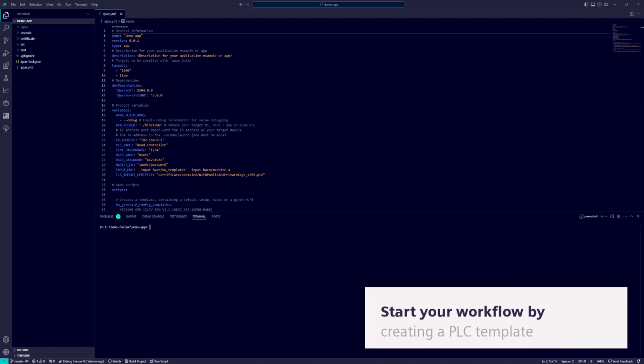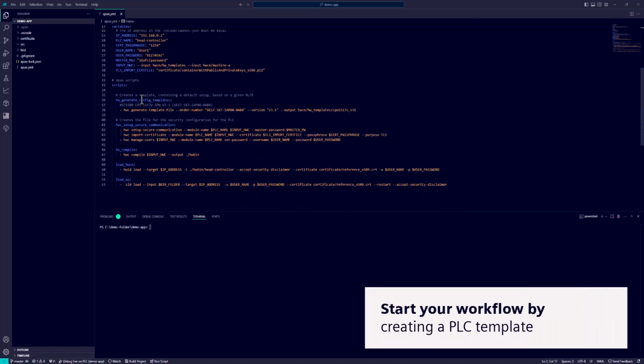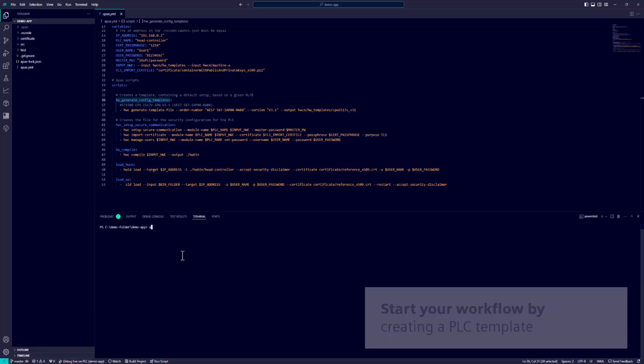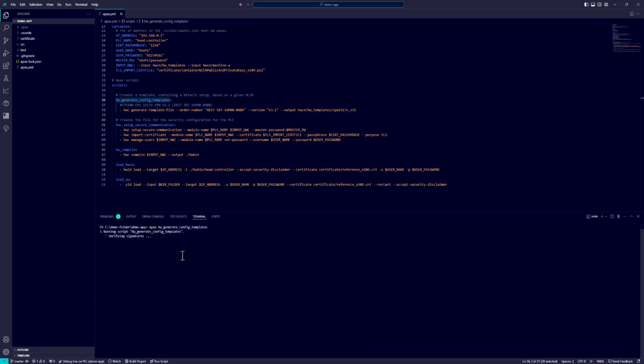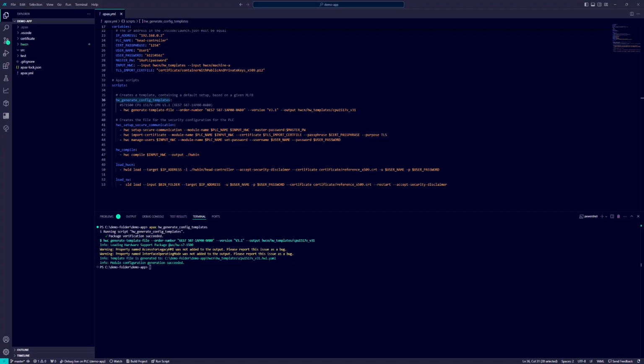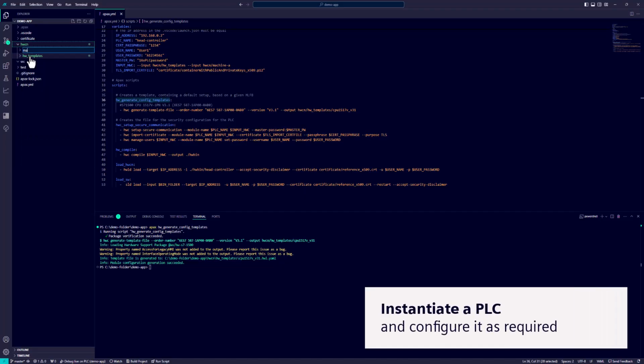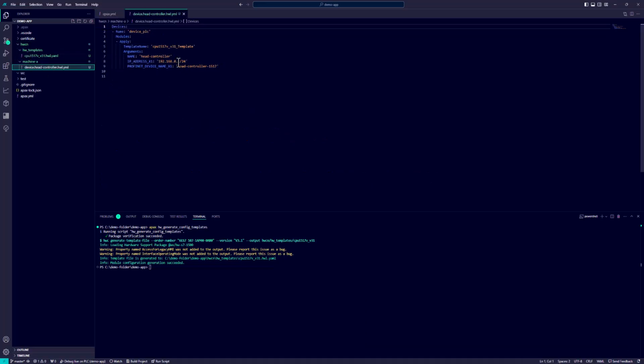The IT-like engineering workflow in SIMATIC AX demonstrates how to engineer a simple machine from start to finish. First, you need to install a prepared template from the hardware catalog. Once installed, you may instantiate and configure your concrete hardware instance by adding a textual definition of your hardware. By referencing the aforementioned template, you are able to benefit from the default presets.